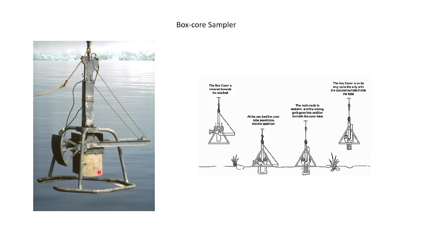Upon lowering on the seabed, see in this picture, this is the box, and we'll lower it till the seabed. Upon lowering at the seabed, it will penetrate a few inches into the soil, up to whatever height we want, based on the box height also. Now cutting plates will be provided at the bottom of that box, and the cutting plates, which were in the locked condition at first, will be released while lowering the sampler.